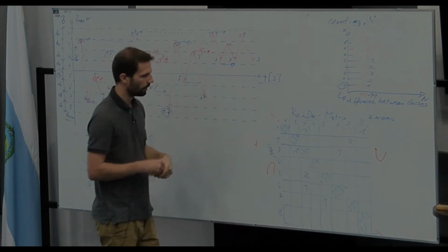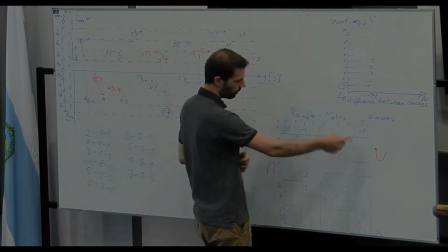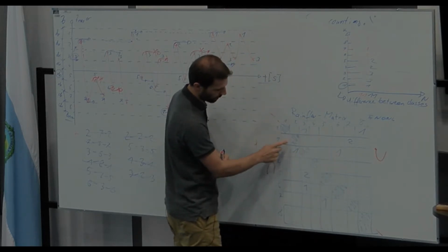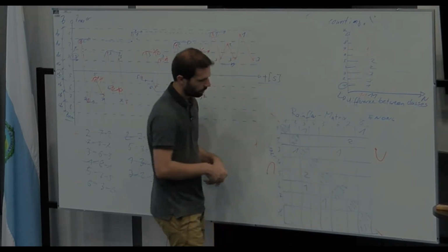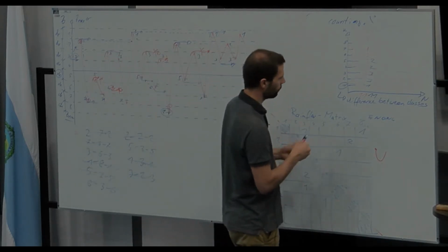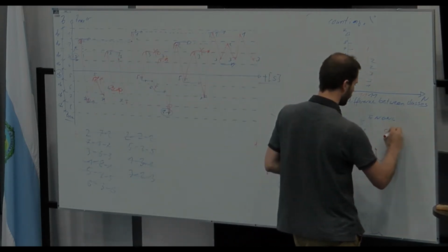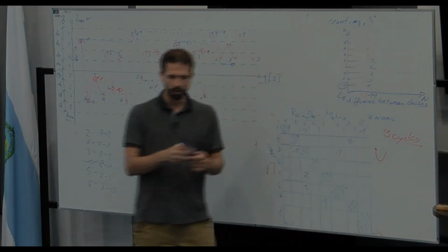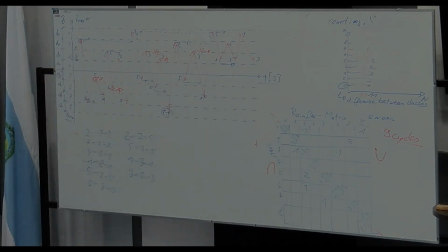So we can go again, we see here we have a whole amount of cycles which are 2 plus 1 plus 1 plus 1 plus 1 plus 1 plus 2. So at the end here we just have 9 cycles. But these 9 cycles are related to the information of the material behavior, so of the cyclic behavior of the hysteresis.